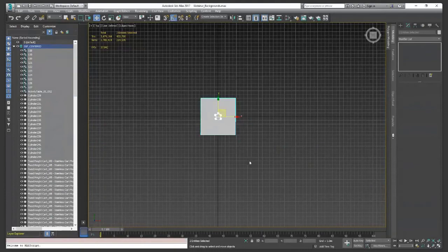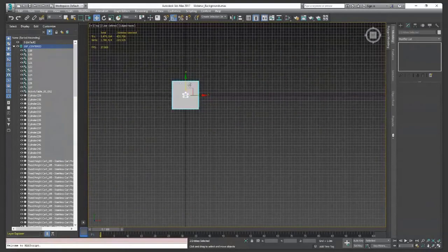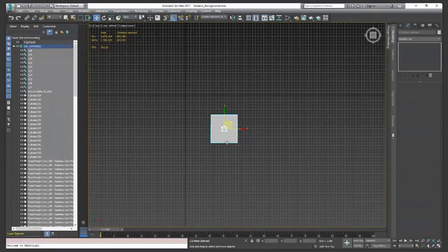In 3ds Max, but in Maya it's exactly the same, if we have this object placed this way, when we export it to Anima to be used as a background model, the pivot point won't be the one we have here in the center of the selection, but will be placed where we have the origin in 3ds Max. So we can control within our 3D application how the pivot point will be in Anima.